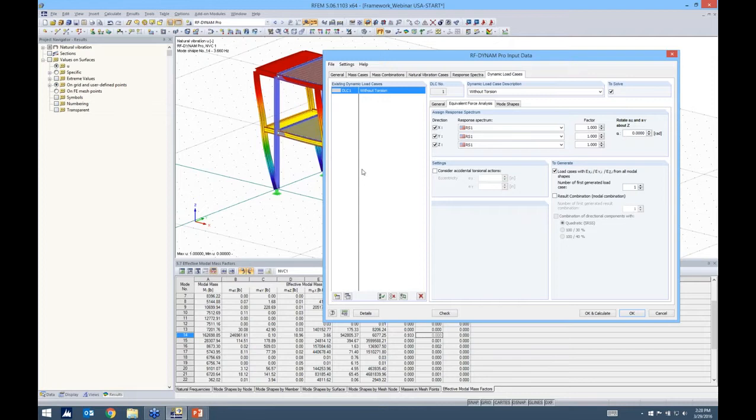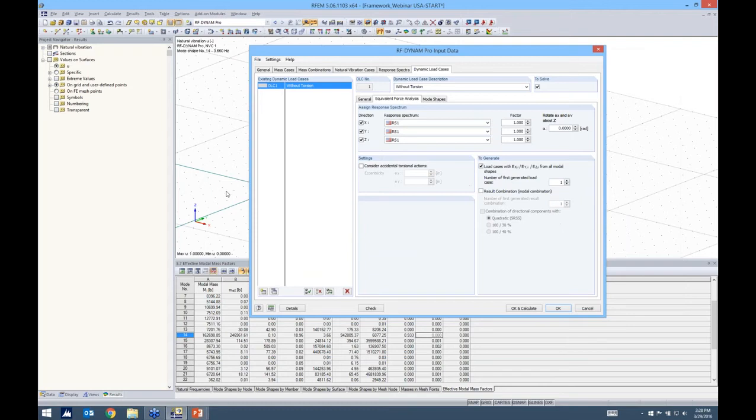So here you can actually rotate your forces about the global Z axis as well with the structure. So that's useful, so you don't necessarily have to be in these direct coordinates. Right now we'll go ahead and leave the accidental torsion off.